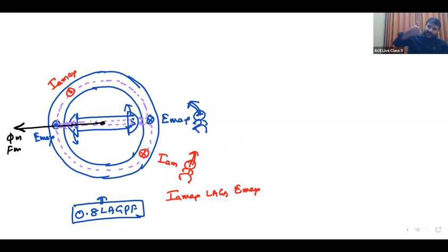Now, then to draw the phasor, what to do? EMF phasor, apply the thumb rule. EMF is always maximum under the pole only, whatever may be the power factor. Armature current is there, na? Current phasor changes, phase changes. But EMF phasor is always the same, because always under the north pole EMF is maximum. South pole maximum. Apply the thumb rule.